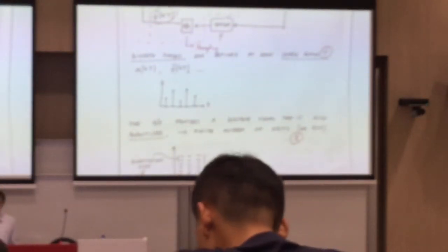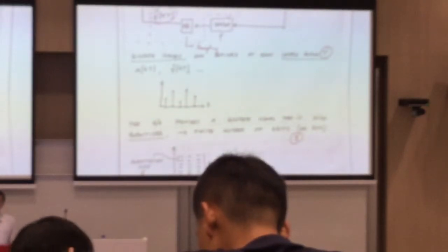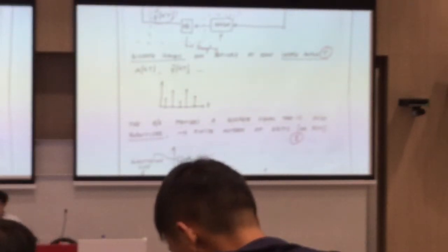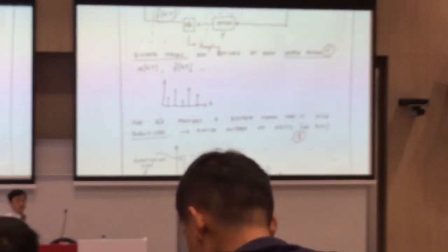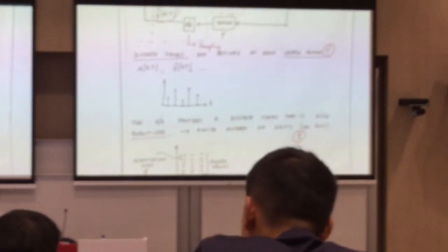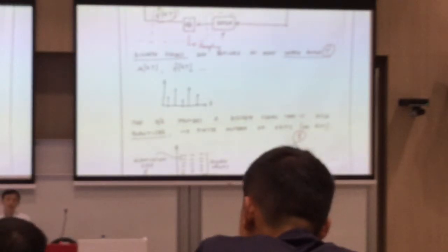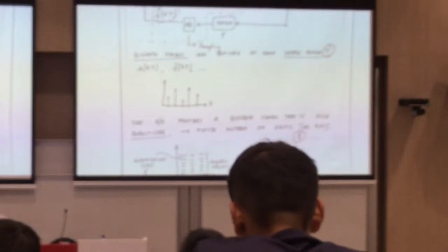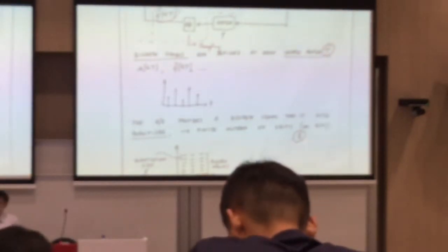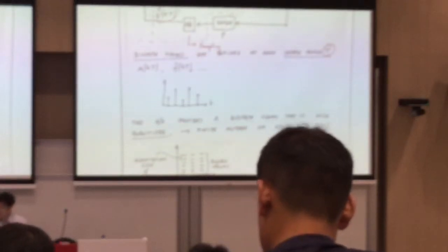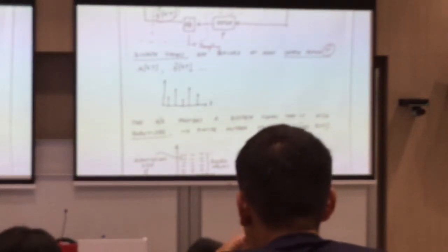For the discretization, basically you need to take care of the sampling period or sampling frequency. If your sampling period is very small, then the gap between your analog and digital signals will be very small. But if your sampling period becomes bigger, then you will have some other issues. We are going to further elaborate on this period or frequency at a later stage, including some of the aliasing issues and so forth.